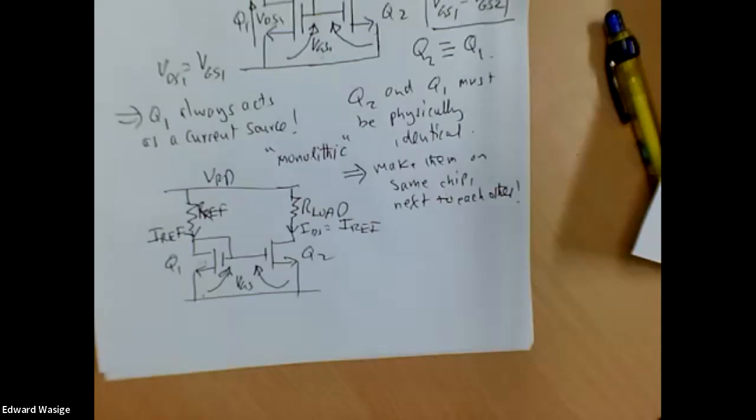No, the resistance of the current source is always high. So we know that the current source has a high resistance, and we'll see why it's useful in the amplifier circuit. We'll see how to use that high resistance. We've looked at it briefly, but we use current mirrors in the amplifier to get that high resistance. So if you just bear with me, I'll come back to your question in a few minutes.